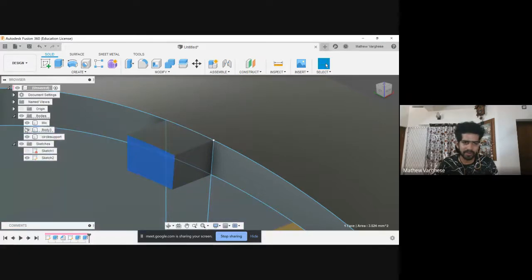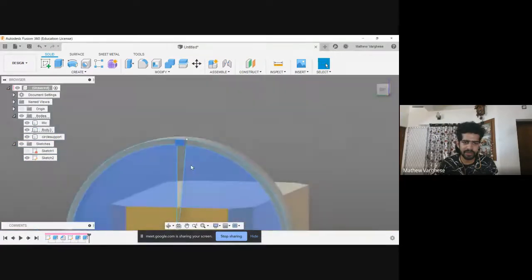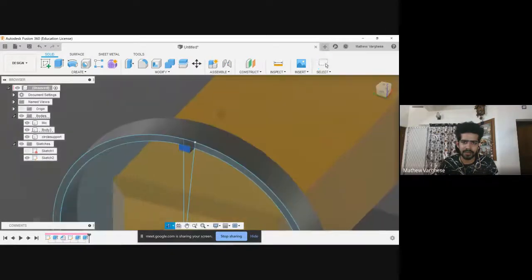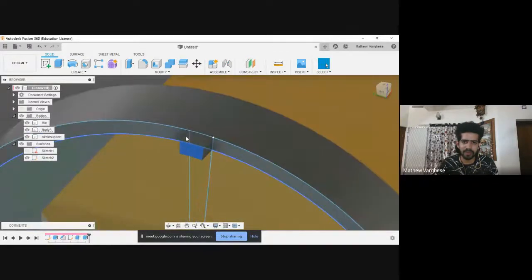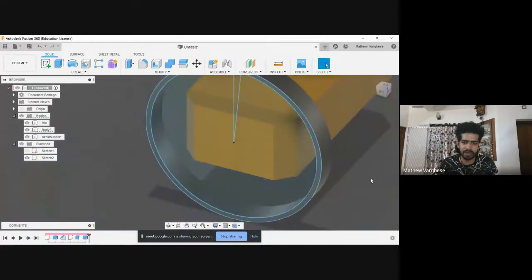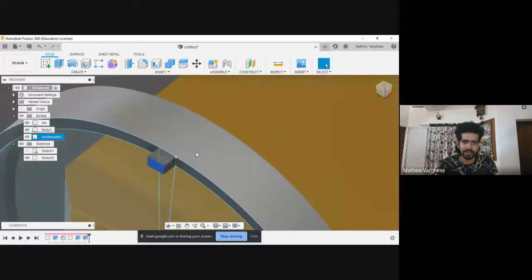Before that, there's one more thing that you should be thinking of. Like only one rubber band wouldn't do. You had to put it all over this place. So I'll be making this one body and copying it to this circular path, 3 or 4 of them. Okay. So I'm building on this, but these are 2 separate bodies. Fine.